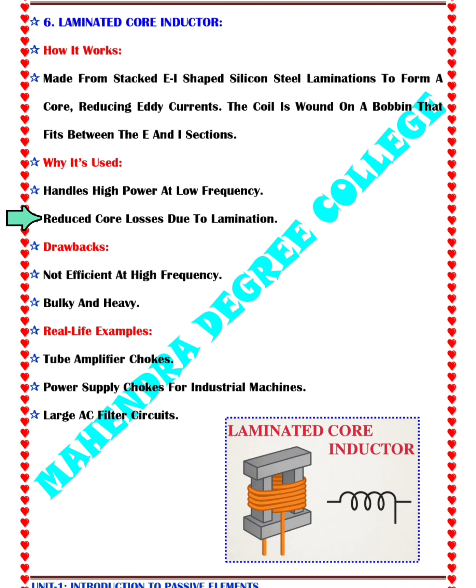Reduced core losses due to lamination. It means laminating the core, stacking thin sheets of steel with insulation reduces eddy current losses.